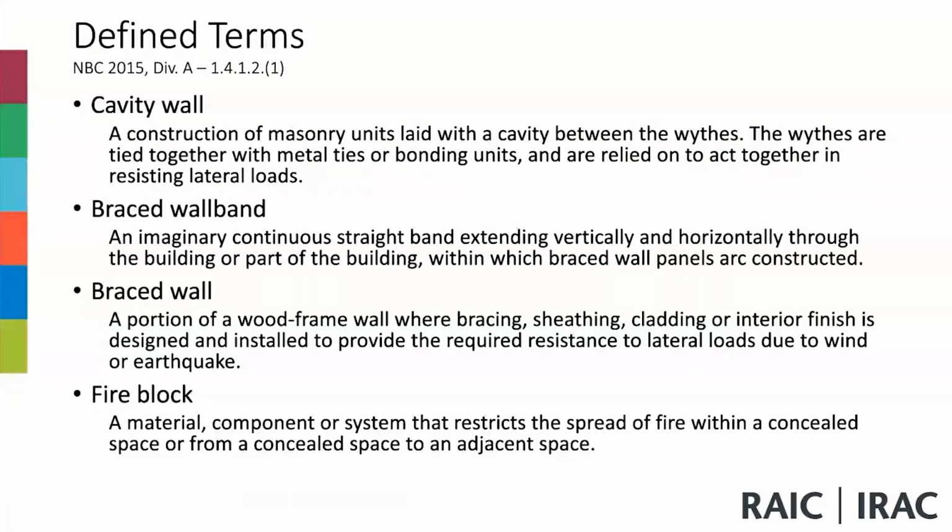Fire block, it's different than blocking, and we showed you this morning what the blocking is used for in the different parts of the building. However, fire blocking is used to subdivide a combustible concealed space in order to restrict the spread of fire within that combustible concealed space. So that's related to blocking.